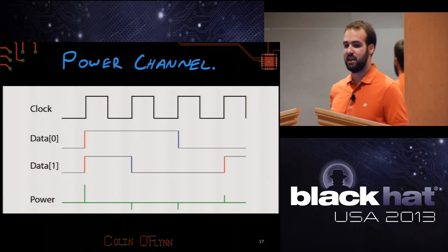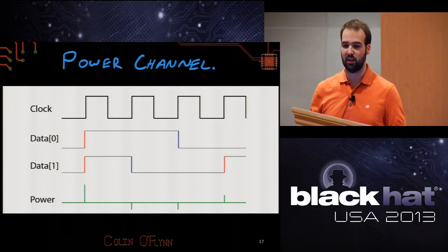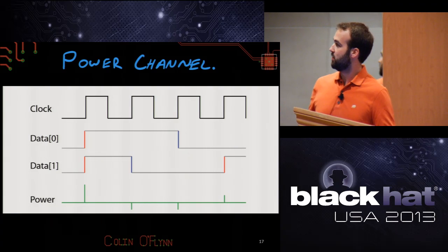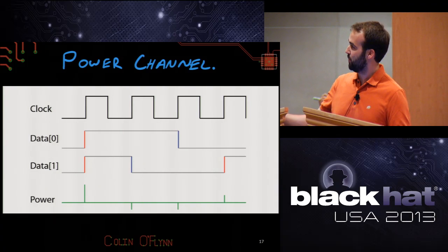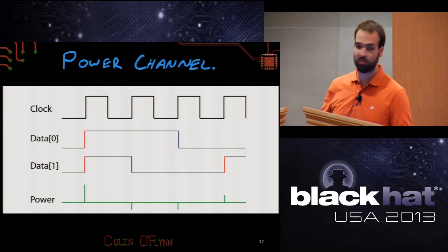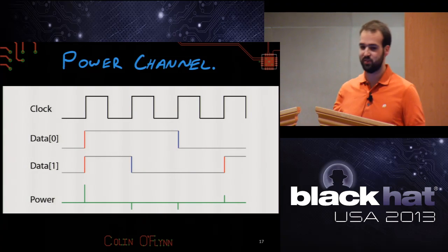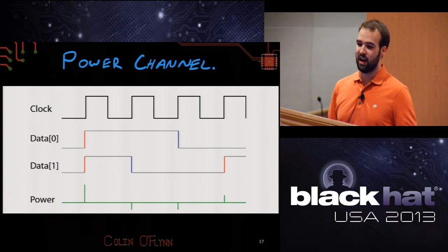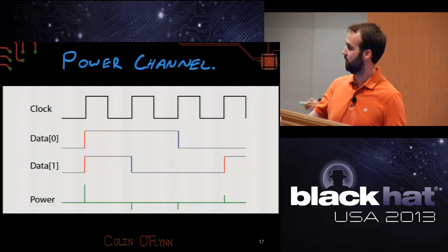Importantly, all of those data lines are switching at the same instant in time. They're switching relative to a clock. So we have a clock on the digital system, and you have the 2 data lines. When that first clock edge happens here, these 2 data lines switch. So on this side, first clock edge, 2 data lines switch, and there's a big positive spike. There's a big positive spike because 2 of the data lines are switching. At the next positive clock edge, only one of the data lines switches, and it's going from positive to negative, so we see a bit of a negative spike.